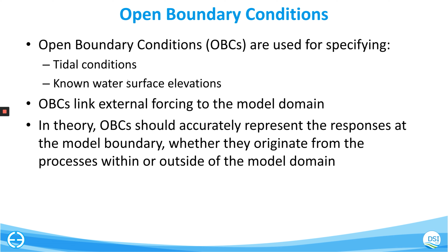That said, there are some systems where these harmonic constituents are provided, but say the tidal station is far enough upstream in a low-lying river estuary that the discharge will significantly affect the characteristics of that tidal signal. And so the harmonic constituents won't really do you any good, because the river is playing such a large role in that system that you can't ignore the effects that large river inflow is having on the water surface elevation.